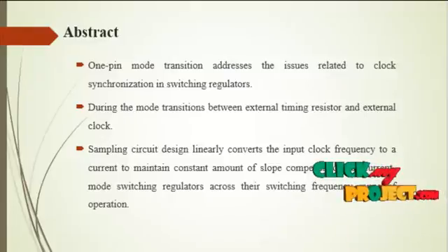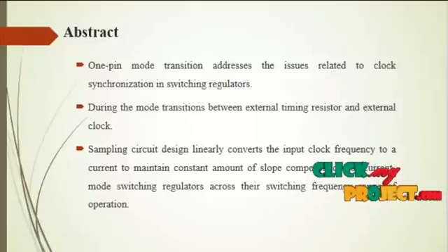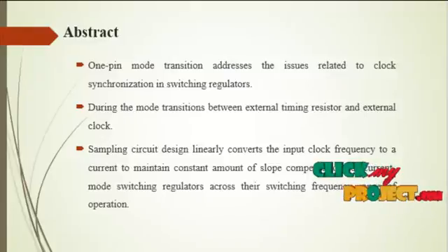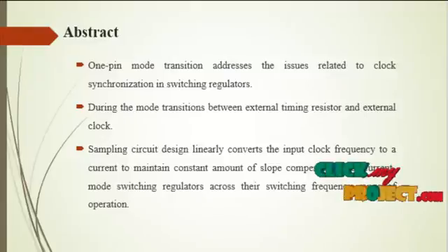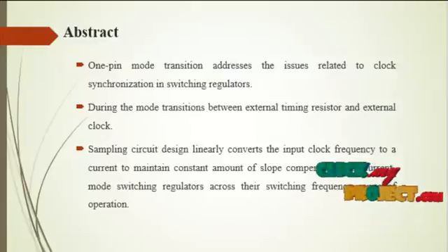In this process, the rising edge of each pulse starts a new clock cycle for the switching regulator. The small size of the proposed design also makes it possible to reduce the die area of the synchronization circuit. The circuit can be used by itself in switching regulators employed in multi-rail systems where multi-phase clock information is not needed.